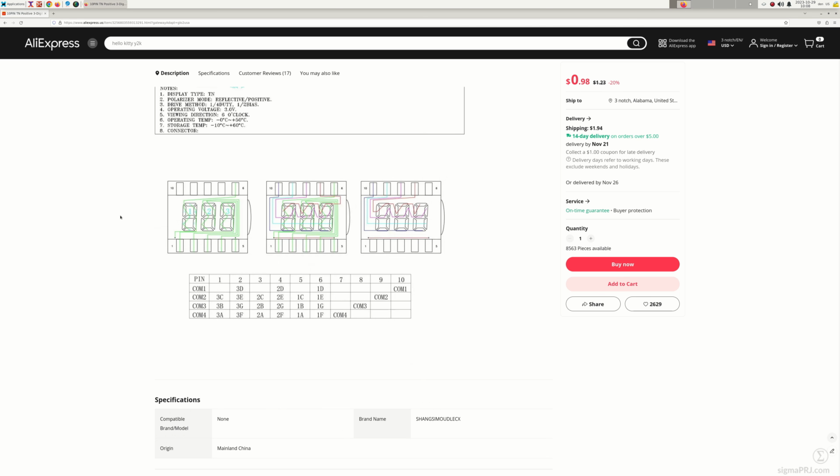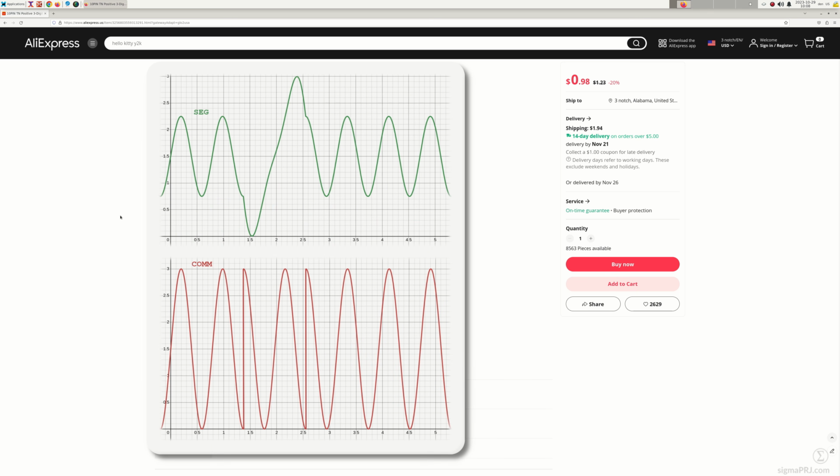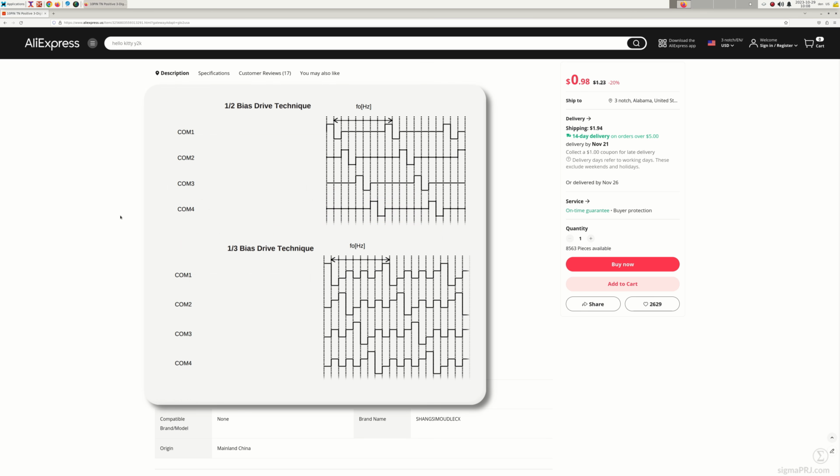In our world, we are working with digital domain, so we'll not have perfect sinusoidal waveforms for our LCD driving signals. They will be defined by discrete values. And appropriate BIAS level will indicate how many distinct voltage levels we will have. Like 1/2 voltage BIAS will let us know that there will be 3 distinct levels. In case of 1/3, there will be 4 levels.